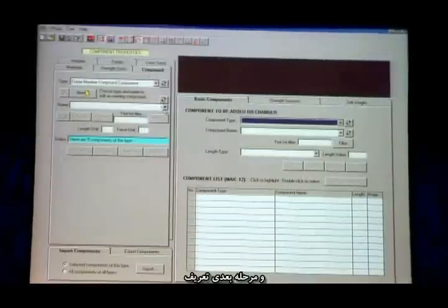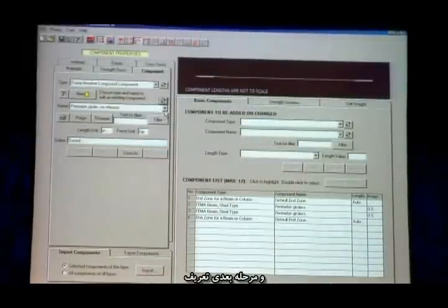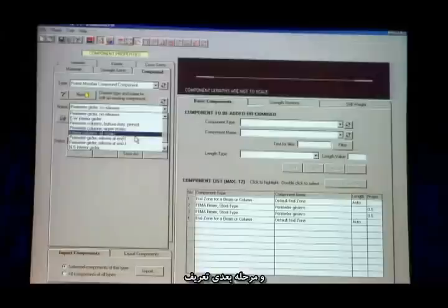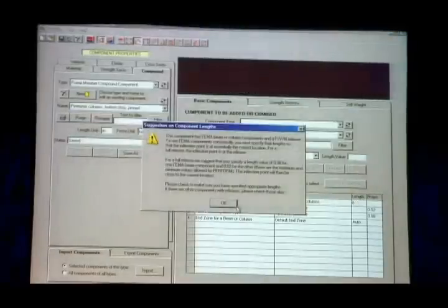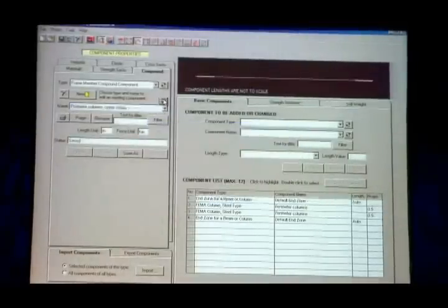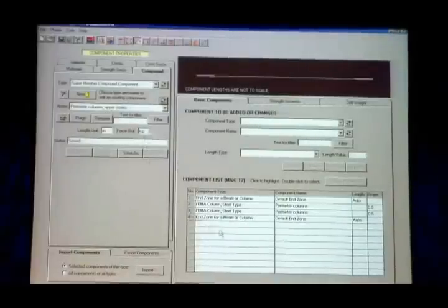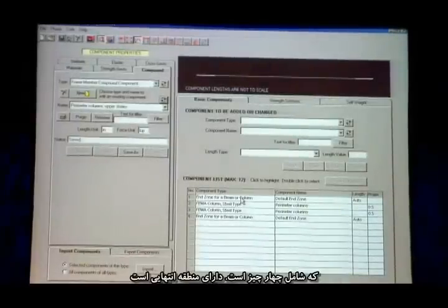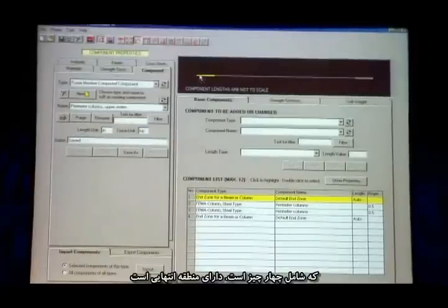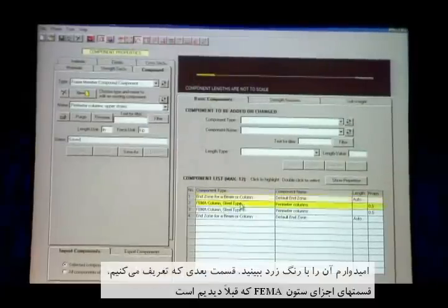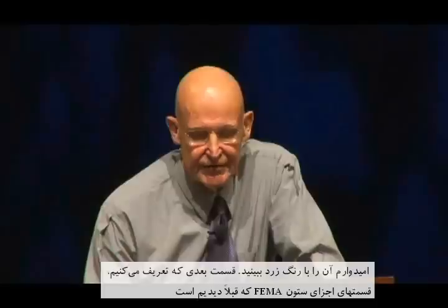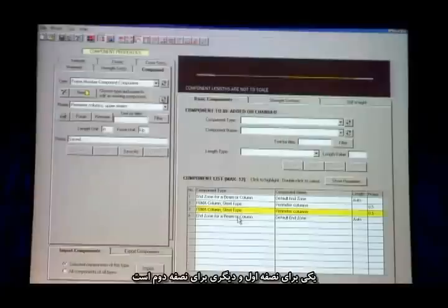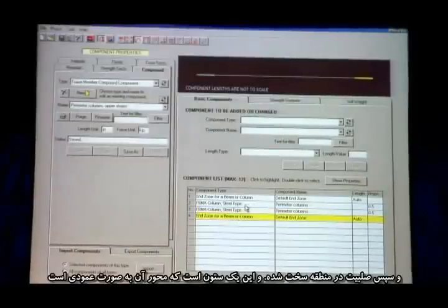And what I'm going to do next is to go into the next thing, which is a column. Let's do the next one. This is going to be a FEMA column, and it consists of four things. It's got an end zone. I hope you can see that in yellow. It's then got one of those things I just defined, what is called a FEMA column component, and I was just looking at it a moment ago. That's for the first half, and for the second half, and then a rigid stiff end zone again.